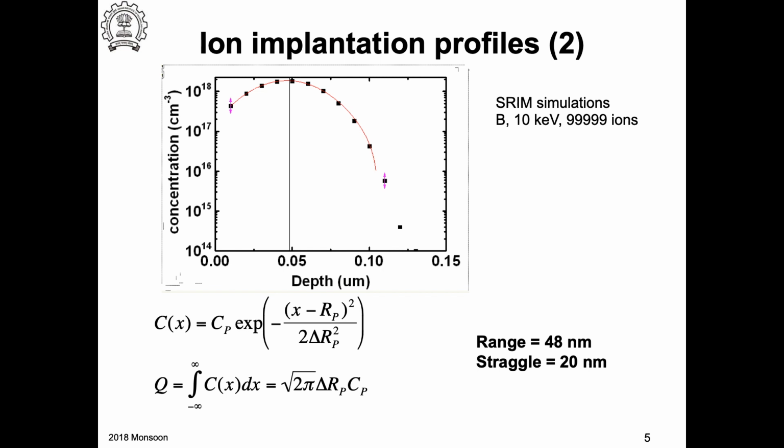For the same energy. These are common in silicon technology. So arsenic is heavy, right? Antimony is also heavy, right? And then you have phosphorus, boron. So this is the lightest of them all. So for the same acceleration voltage, boron will go much deeper.